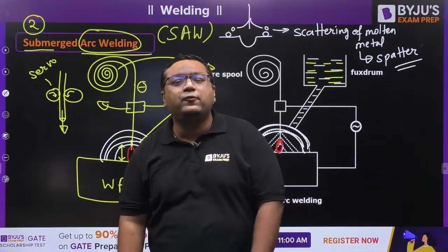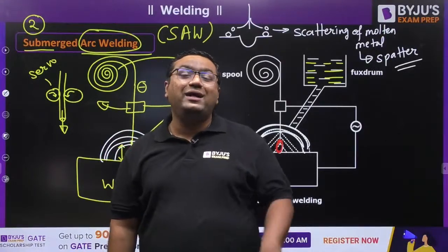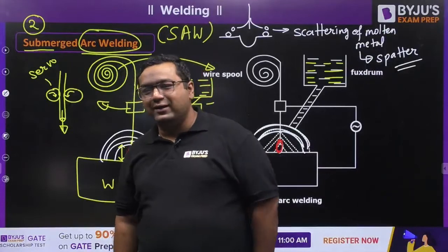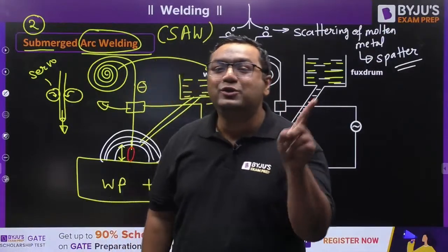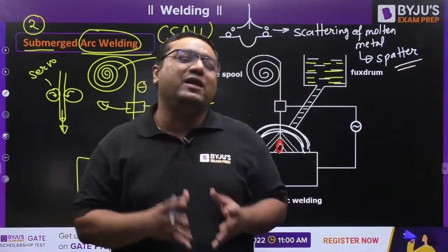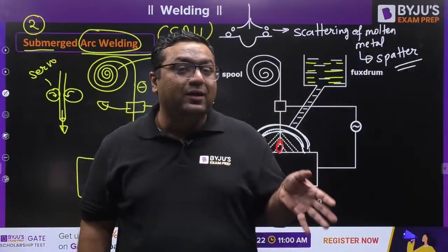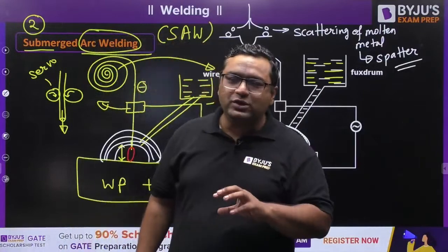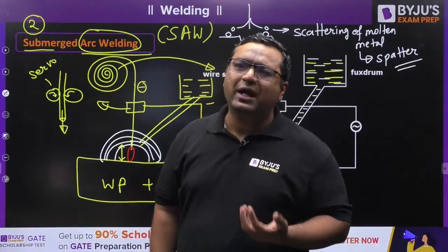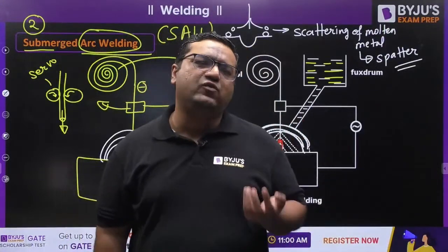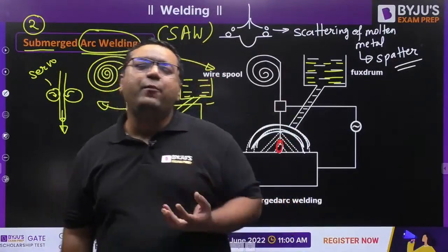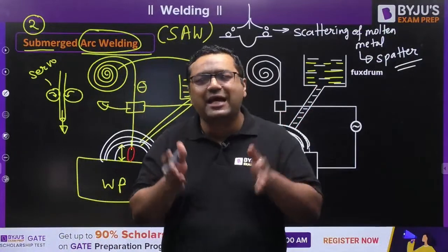And if the welding process is faster, the welding speed is going to be more. We know one more thing, my dear, that the heat affected zone is going to be reduced. Because whenever we get high welding speed, the heat affected zone is reduced, which was the weakest zone. And my dear, failure generally occurs for a welded joint at the weakest zone only. So we always want the heat affected zone to be as small as possible.